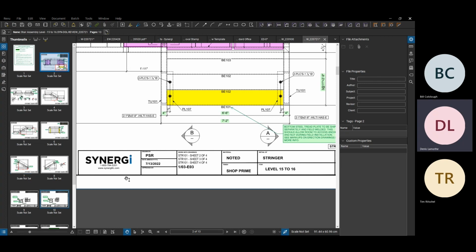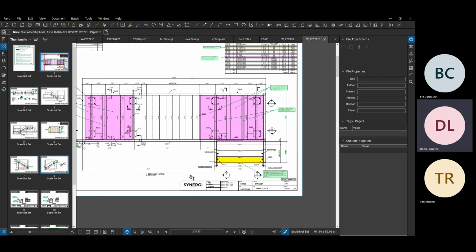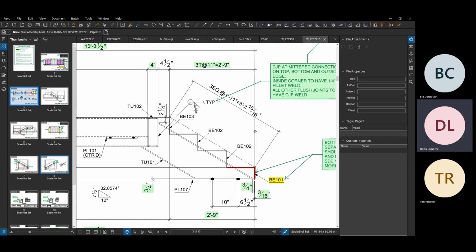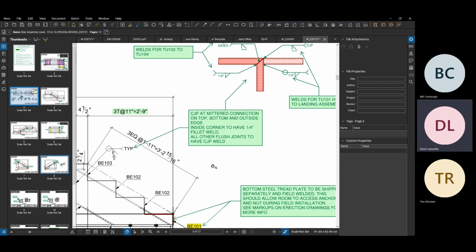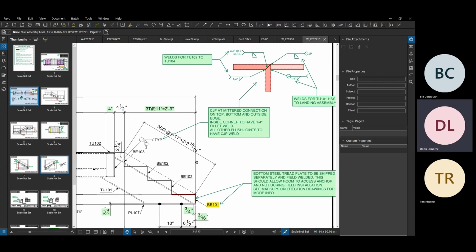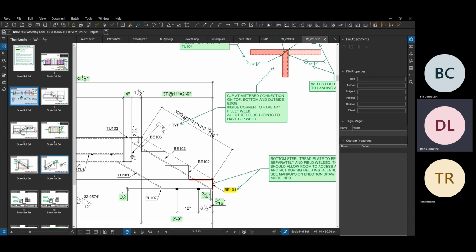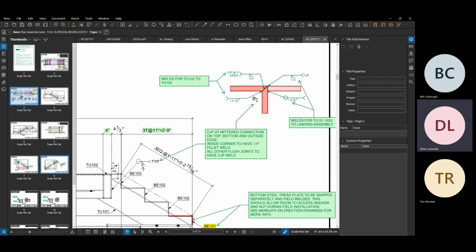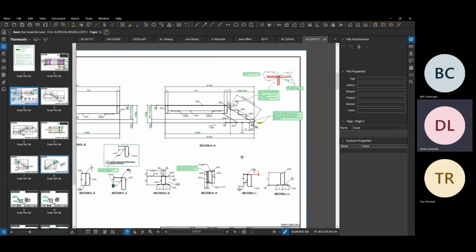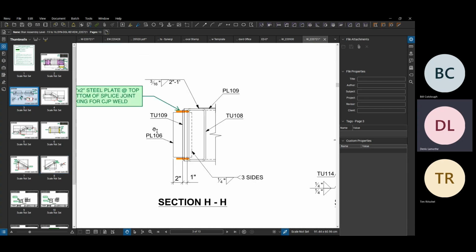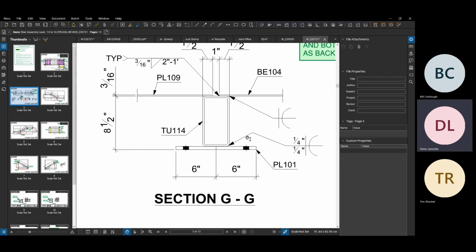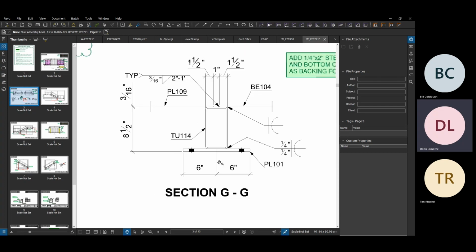We talked about the weld sizes for the erection drawings. It also applies with assembly drawings. If there's any welding, check that the proper weld is displayed, and not necessarily for every single joint, but if there's a component that has multiple different types of welds applied to it, that it's clearly laid out, labeled or identified in some way. If they need to add a quick little detail somewhere, they can throw something in on a secondary page and show, yeah, this is an old splice joint here. That helps to clarify what kind of welds are being used where.